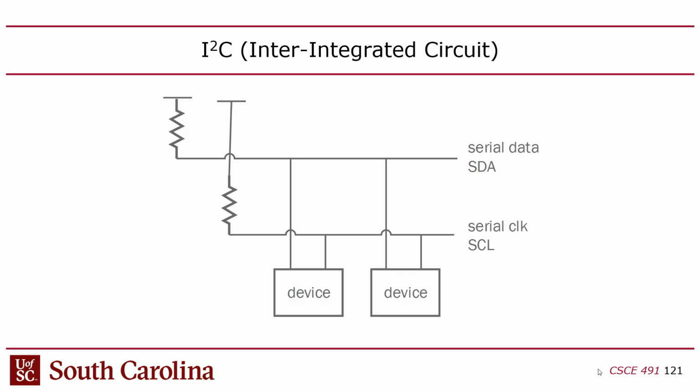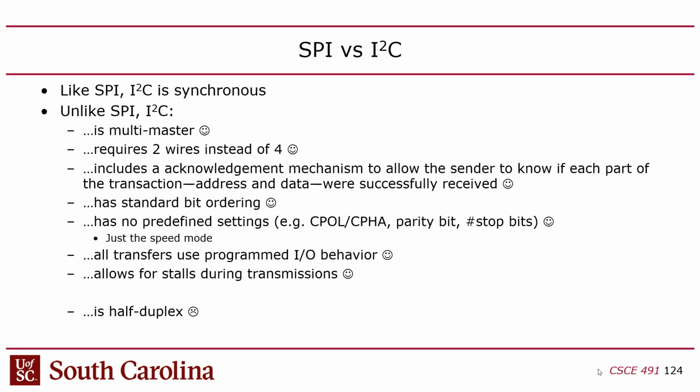So you're going to have 2 separate pull-up resistors on there. And then the devices that you want to connect to this bus, and this becomes like a shared bus, almost like an Ethernet, each device is connected to both wires, to both signals, right? To both nets.